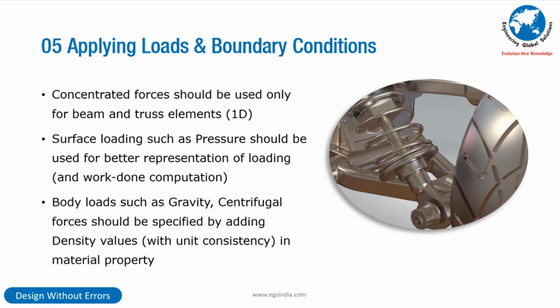It affects your Saint Venant condition, and it affects your work done. Potential energy equals internal energy minus work done due to the external forces. The work done due to the external forces calculation is wrong. If you use surface loading or body loading, it is a surface integral or volumetric integral. Much better. You see where the energy gets frittered away and doesn't really go onto the system effectively, giving wrong results. This is where we need to be circumspect about it.